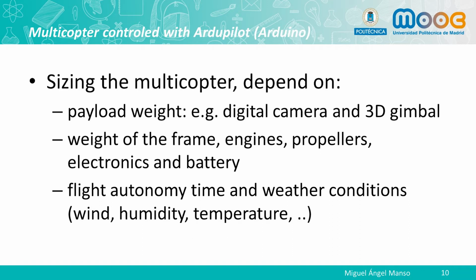Once the combined consumption of all of the motors and electronics has been calculated, ESC, RC receiver, sensors, Arduino, depending on the capacity of the battery, the maximum flight time of the equipment can be calculated. Always keep in mind that the conditions won't be ideal, that the multicopter has to rise, move and land, and this requires extra power consumed.